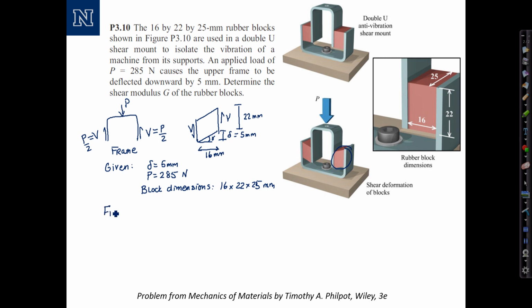What we are asked to find is the shear modulus G, and again, shear modulus of elasticity has units of stress. Since we're working in standard units, I'm going to express this most likely in megapascals. Sometimes for shear modulus we would use gigapascals because they tend to be very large in megapascals, but this isn't true for rubber, which is a relatively flexible material.